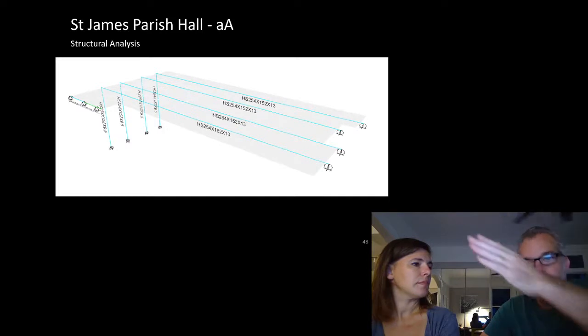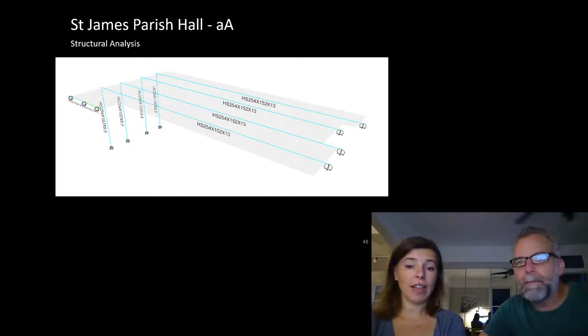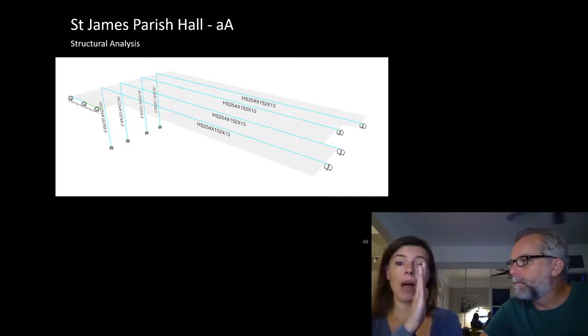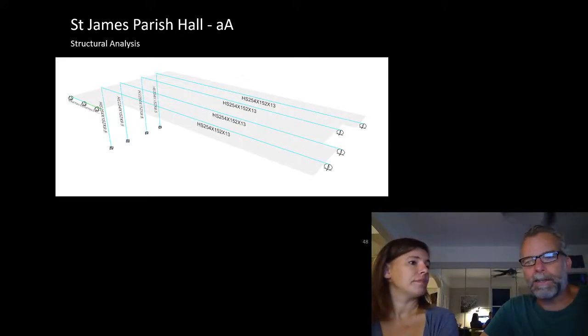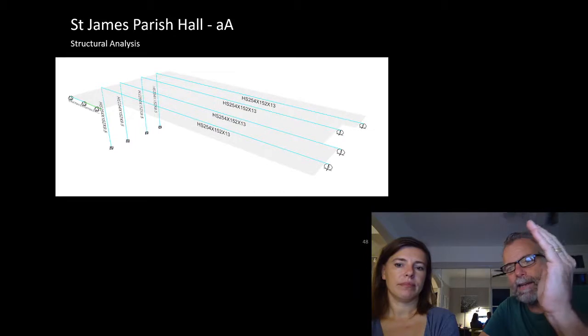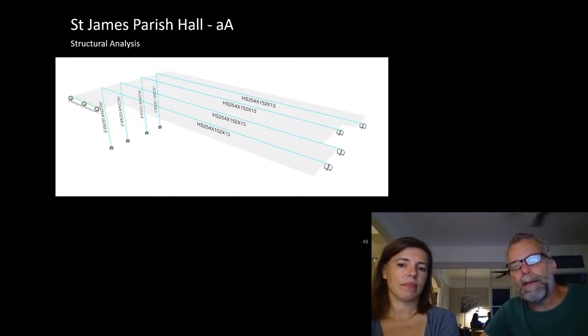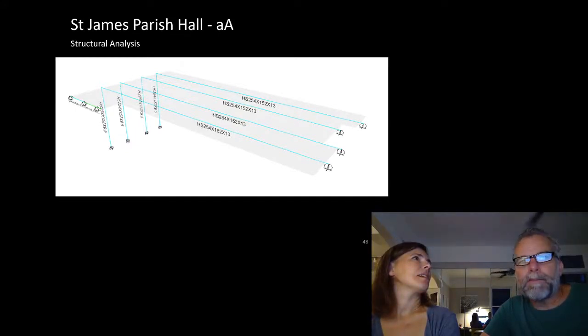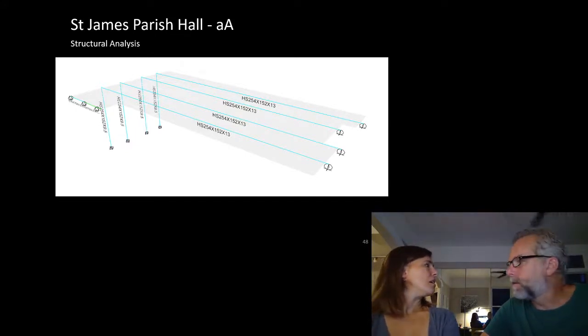Glass is thin, and it can bend. Our guard deflection, 40 millimeters, is what's allowable for a guard that's only a meter tall. And a typical curtain wall deflection is L over 180. So it can tolerate quite a bit of movement out of plane. It's in-plane racking that's a real challenge for glass.